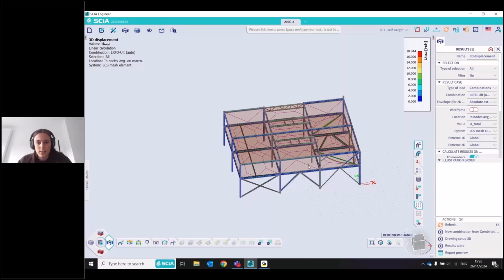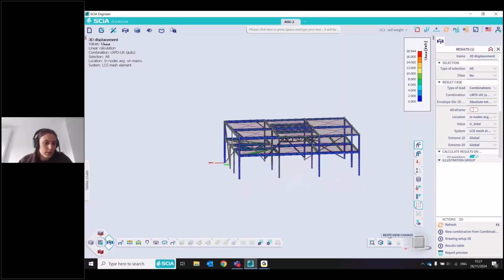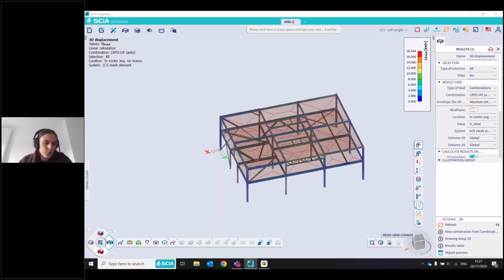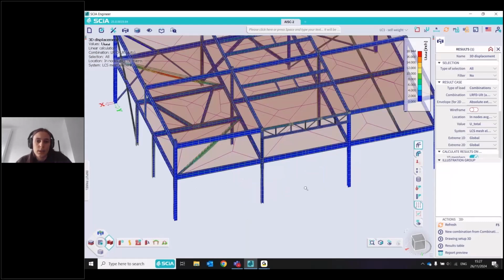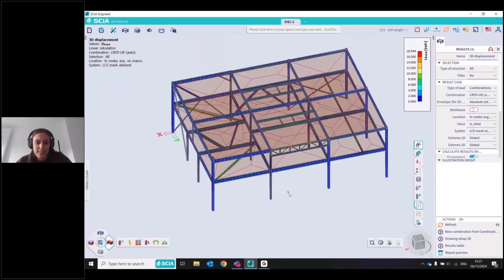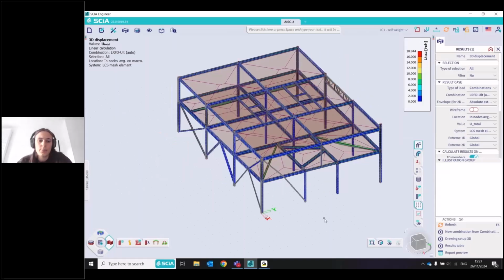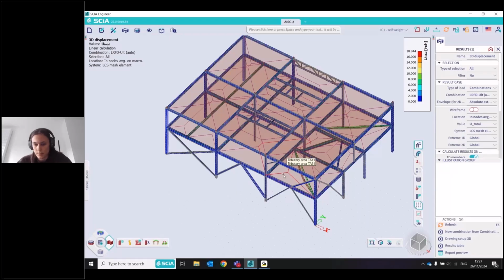And these results we can then use to go into more American-specific results, which we will find in our steel design. But before we go into steel design, it's really, really important that we think about buckling and buckling settings. For getting any correct results from your steel design, it's really important that we put the correct input in there and define the buckling systems correctly.